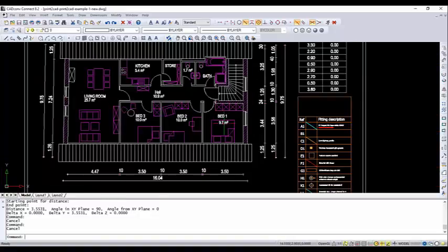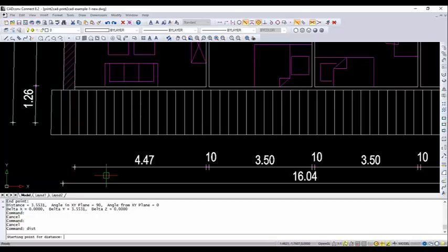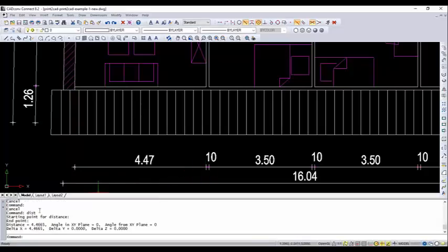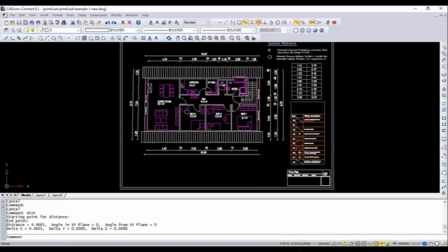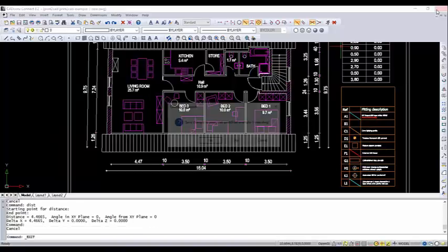And you see, everything we calibrate is better, but of course this distance will not be perfect because we did not put calibration points exactly; only the mathematical methods change the quality here, but the quality is now much better. It is almost 3.47, but as I told you, this is only the mathematical methods making it better. If you define every point on these dimensions as a calibration point, you will receive a perfect drawing. Yes, but it takes a little bit of time, I know.